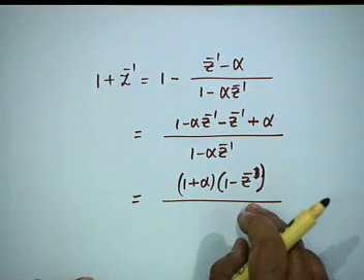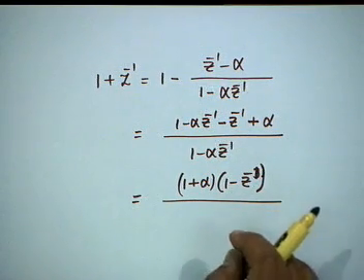For example, in a band pass filter, the numerator would be 1 minus z to the minus 2, and because it is third order, it will be raised to the power 3. In a band stop filter, you can't say this. Okay? Band stop is rejection at some intermediate frequency. So, it would be slightly more complicated.